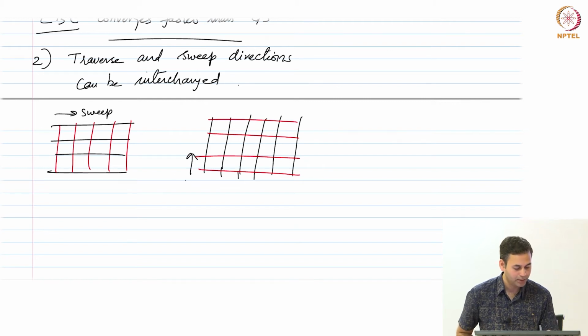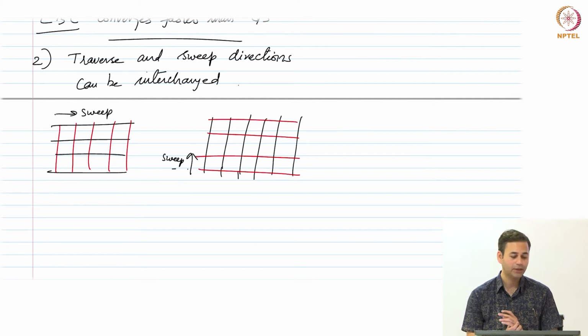Along x and along y. So, you could even alternate this because the TDMA will bring in the boundary condition information to the interior cells in one go. As a result, you would get convergence much faster. I think your next assignment would involve these things. So, your TDMA function has to be generic enough such that you can do all these patterns.